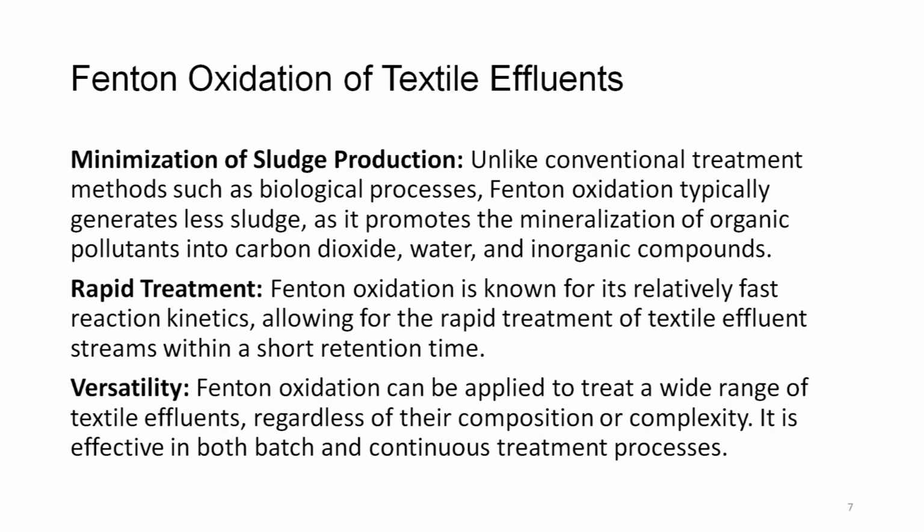Minimization of sludge production. Unlike conventional treatment methods such as biological processes, Fenton oxidation typically generates less sludge, as it promotes the mineralization of organic pollutants into carbon dioxide, water and inorganic compounds.